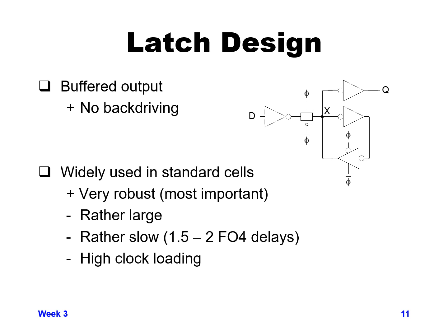And it does have more clock loading because you have both a PMOS and an NMOS in your pass gate, and you need to create a clock and a clock bar version of your clock in order to make sure that you clock both sides of the pass gate. So, it is a good design, but there could be reasons why you might want to use one of the other designs that we talked about earlier.